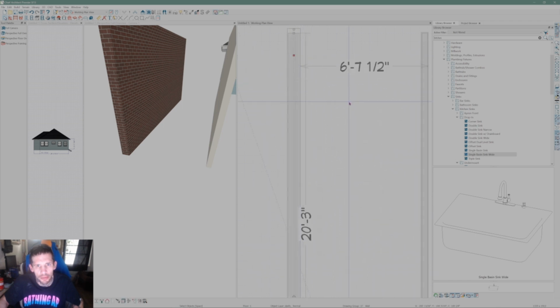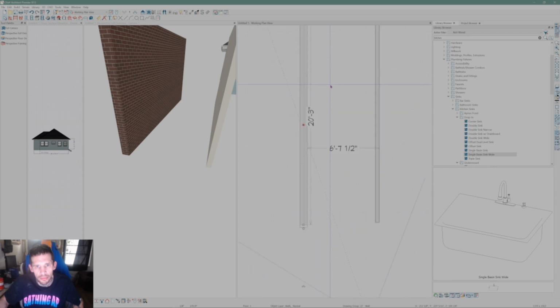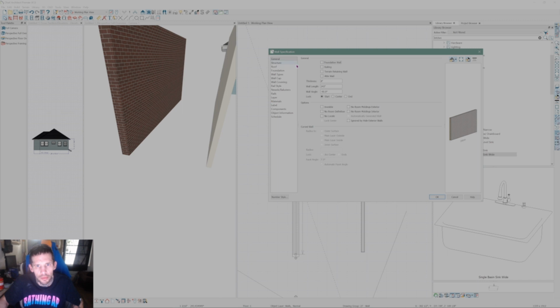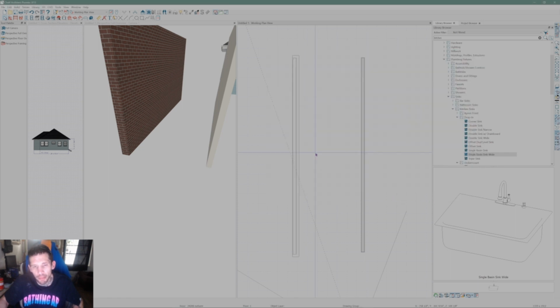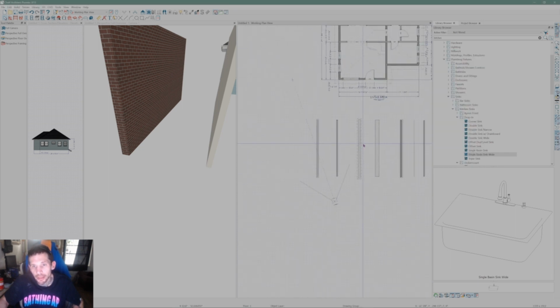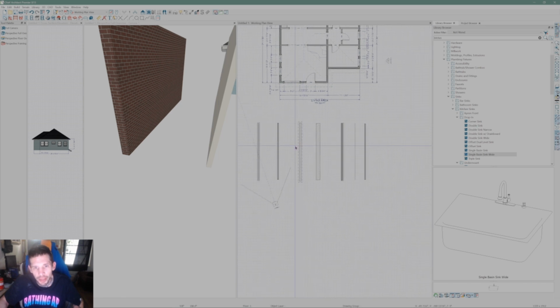See, and you can see. Let's open it. Wall types, and it's the dark brick 3.5 inch that we just made. Okay, so that's how you make a custom wall. These are the wall types. Each of them has its own detailed features to an extent, and if you'd like me to break it down even further, just say so in the comments and I'll get it to you.